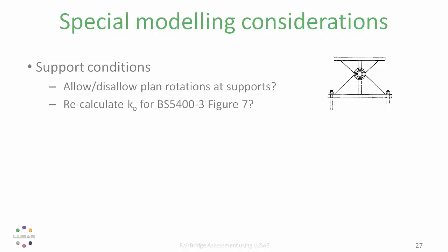Second, our FE model includes variable flange sizes, which of course the code doesn't, and it could have included corrosion, even local corrosion or damage. That's going to have an effect on the calculated moment of resistance, which isn't easily incorporated into the manual calculations.